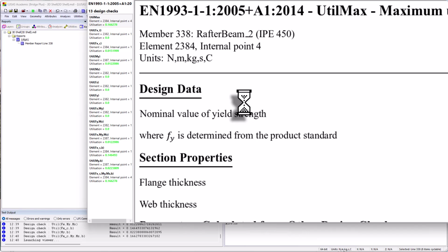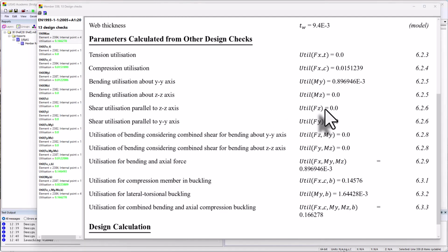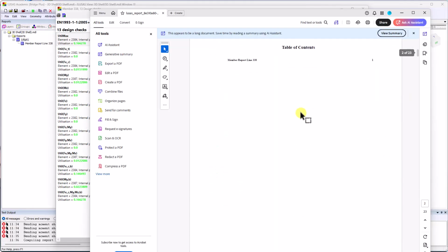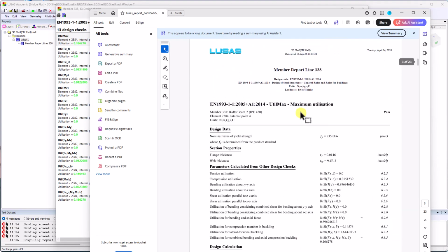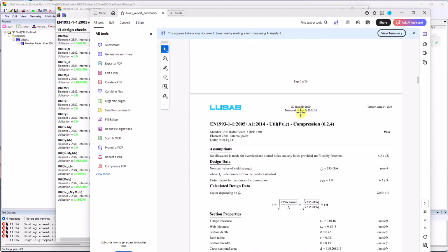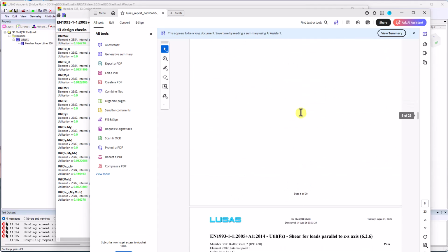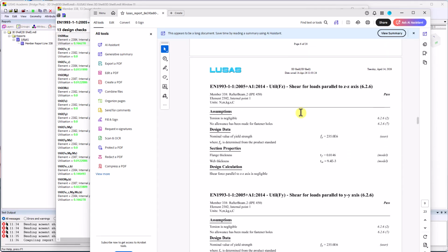This function shows the detailed EN1993-1-1 clause by clause design calculations for the selected member, including the applied section forces, section classification, the calculation process for each resistance value, and the relevant clause references and formulas, all presented in order. Using the Add to Report button within the report, you can also add these calculations to the overall model report.